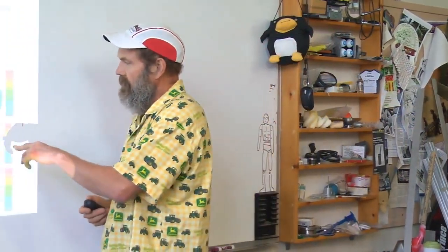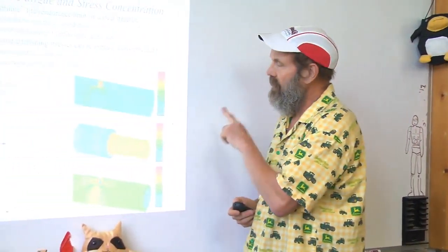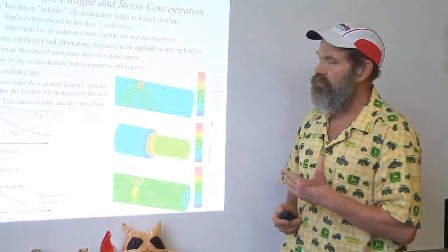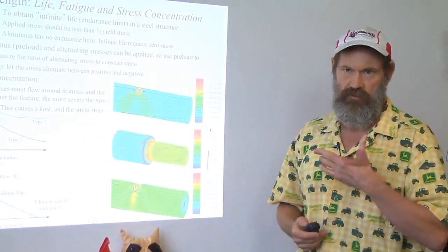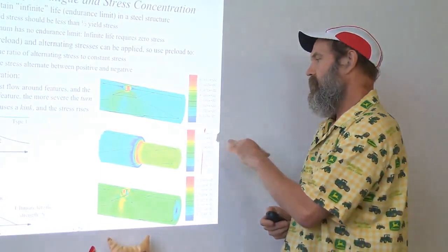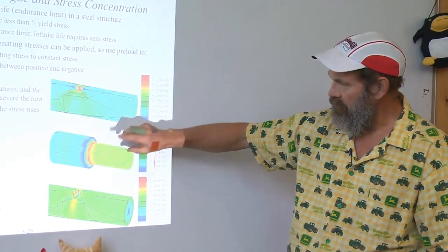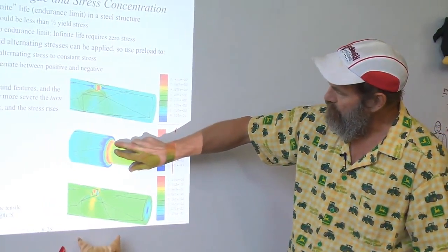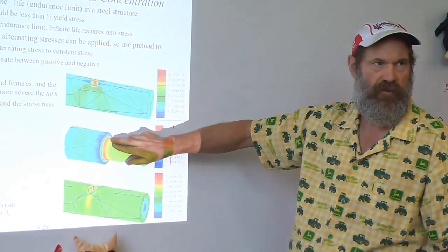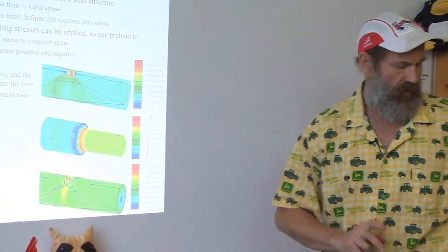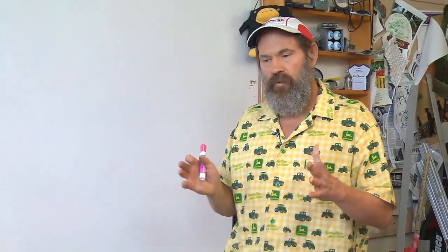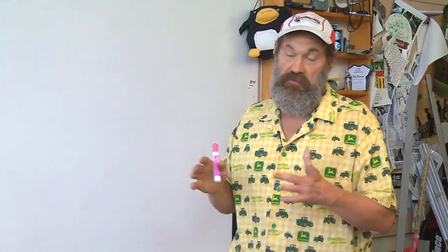Now, when you're doing finite element analysis, you've got to be very careful that the mesher, either inherently inside of it, will do a very fine mesh, or you have to control the size of the mesh with the parameters you can use to give you accurate results. One of the very important ways you can know how fine the mesh has to be: most finite element programs will allow you to just use the default, or you can tell it to go finer.